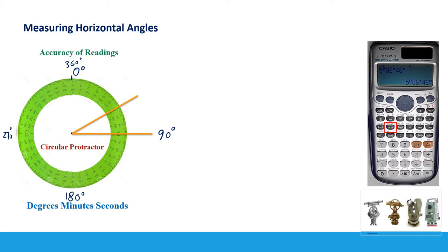So to measure this horizontal angle, in this case, between these two directions, if you look here guys, this is 0, here we have 10, 20, 30, 40, 50, 60 here. So we have 60 degrees here, 90 degrees here. So it would be very simple to say, okay, this angle, let's call it alpha, which is 90 degrees minus 60 degrees, and the answer would be 30 degrees.